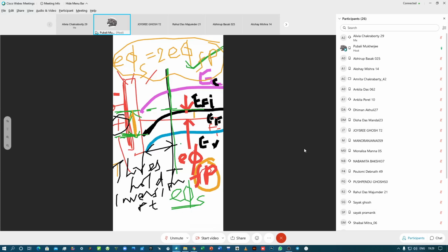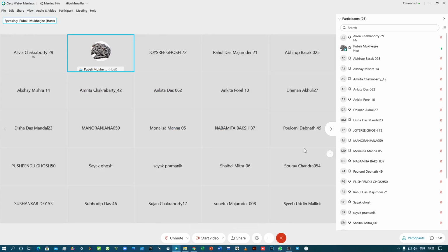Around 8 to 10 pages I have taught you. The same explanation is given with respect to your n-type substrate also in the book. If you're interested, you may go through it. Things would just be the reverse. Where you're getting positive charge, positive gate potential, there you would have to apply negative gate potential, and the band bending would be changing just in the opposite manner as was happening in case of your p-type substrate. Okay.